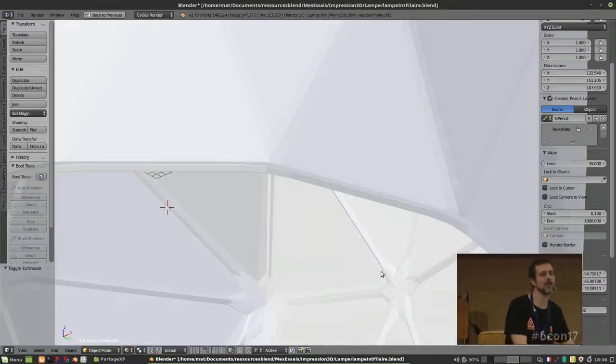The only thing is that you have to understand where the origin of the family is, and locate the origin of your project at the same place. So you move all your project in Blender so that the 0 of the project will be where you want the 0 in Revit. Once you found this, it's quite straightforward, because anytime you move a beam in Blender, you export it again, import it again in the family, and in your plans, everything moves. So it's much better than what I did before with Archicad. It's not perfect yet, but it's quite working.